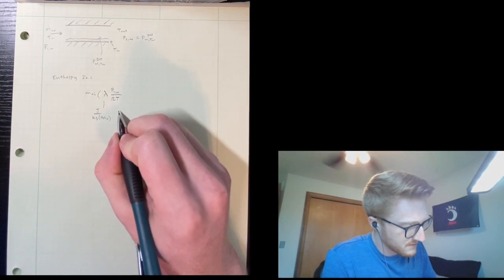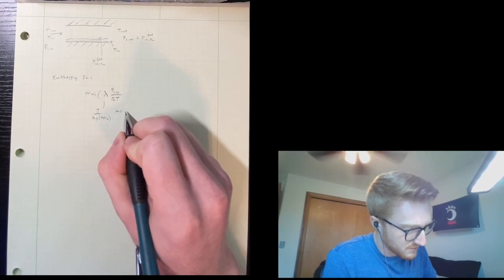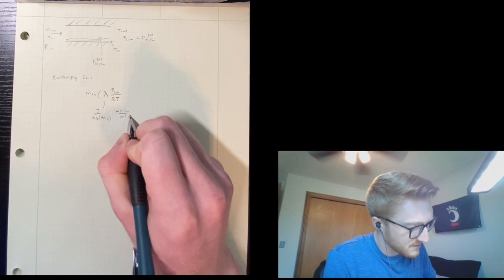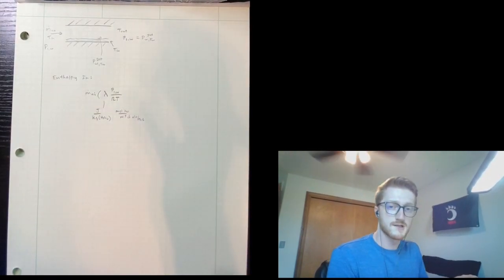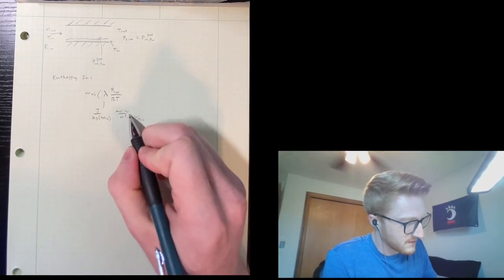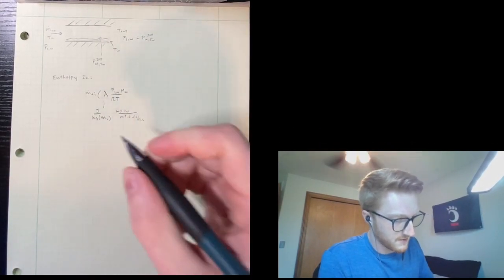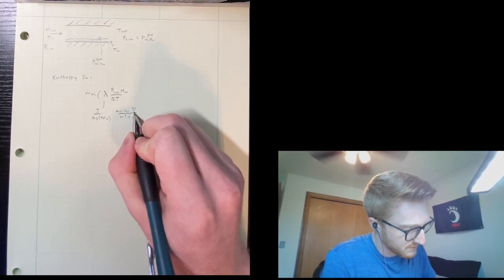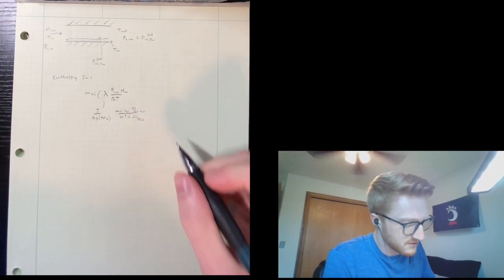This was going to be in moles of water per meter cubed of the air and water mixture, but we want just the amount of water in the air, and we also want kilograms. So we multiply by the molecular weight of water, giving kilograms per mole of water, which allows us to have kilograms per meter cubed.